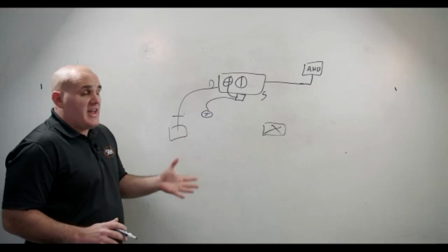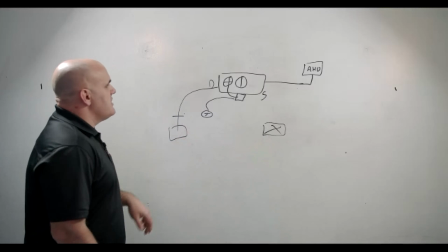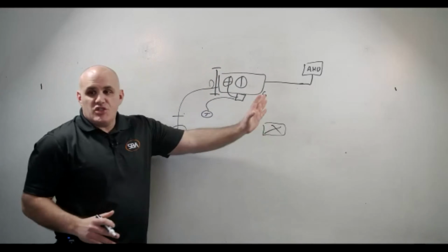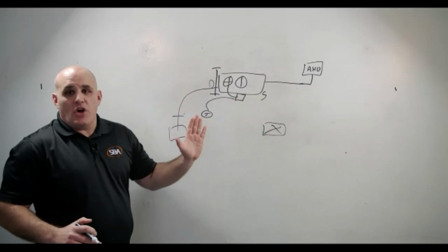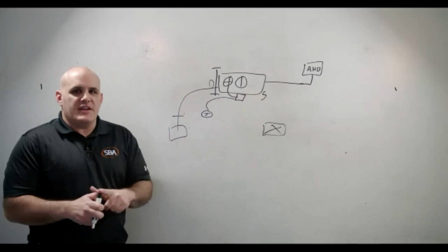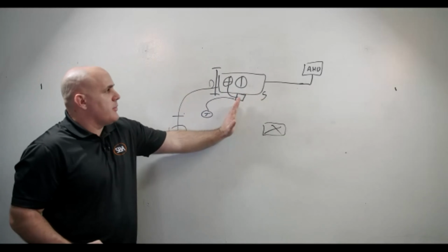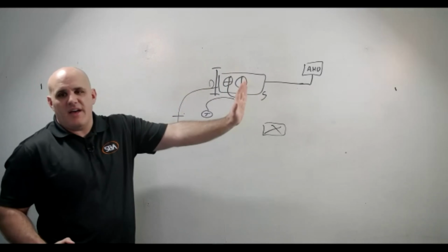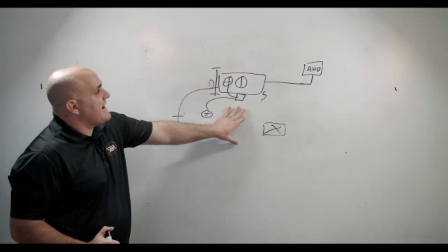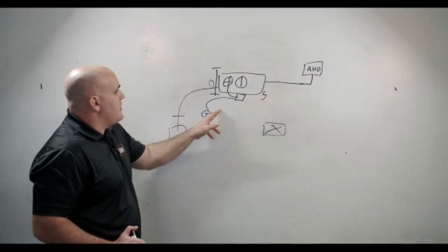Once we've checked all that, you're usually going to resolve the issue by the time you get to here. But what I hope you all saw is how I logically walked through that. First thing I determined was that it was indeed an issue with the terminal unit and not some higher level system, right? You all saw that, right? Okay, the next thing is I started working my logical path down the unit.